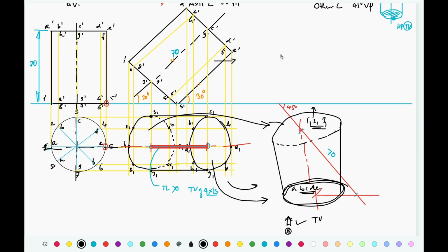So when you project and have intersection with the projections from the front view and locate the final intersection points, while connecting those points, this is the ABCDE face, so this is going to be the top face that you are supposed to draw visible.